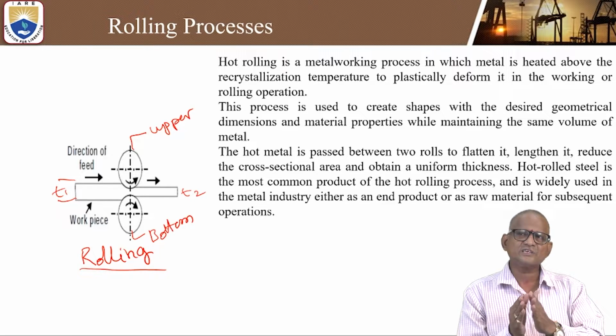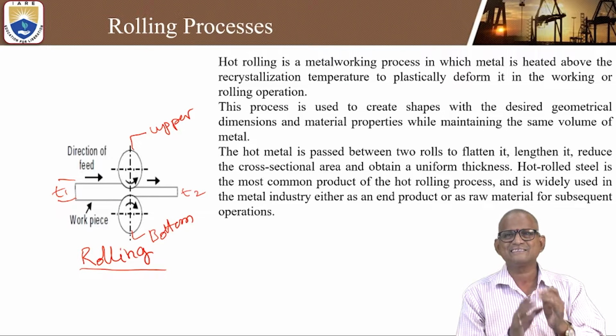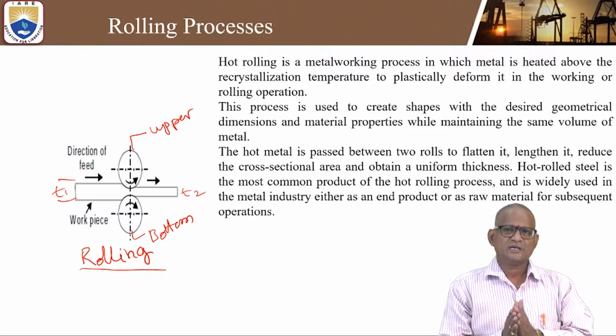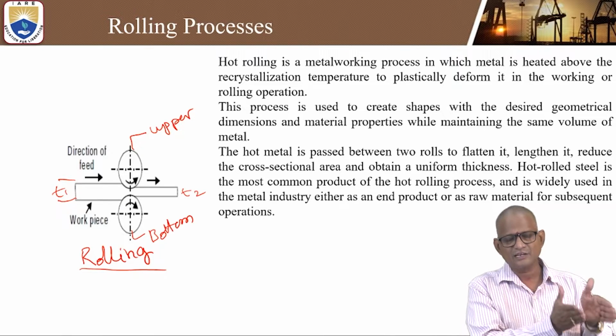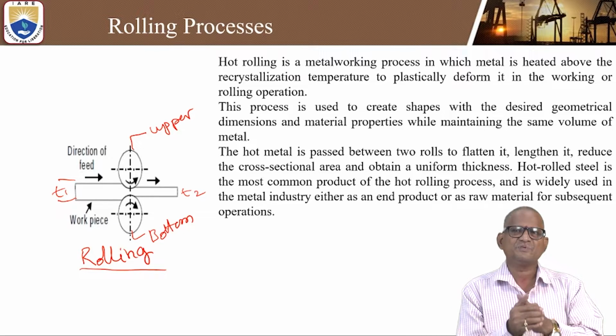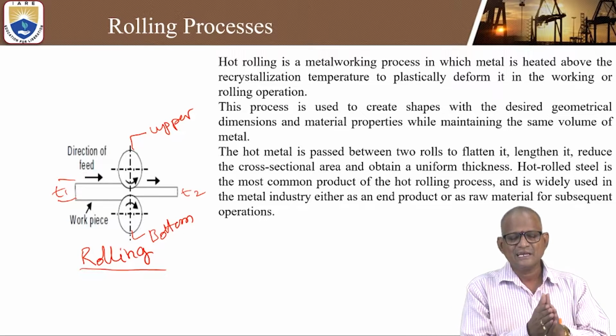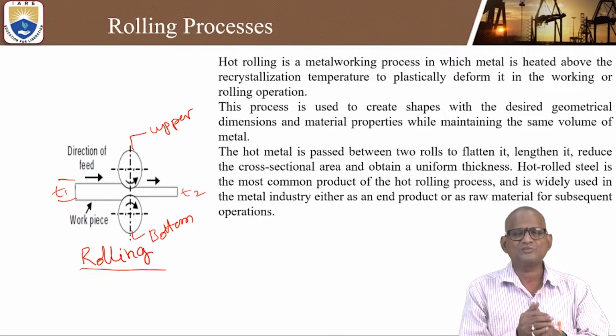In hot working, the first and foremost application is the hot rolling process. Steel rods and ingots to billets, and billets to small square rods, can be made by this hot rolling process. It is a sequence of processes. Continuous passes can be done in hot rolling.